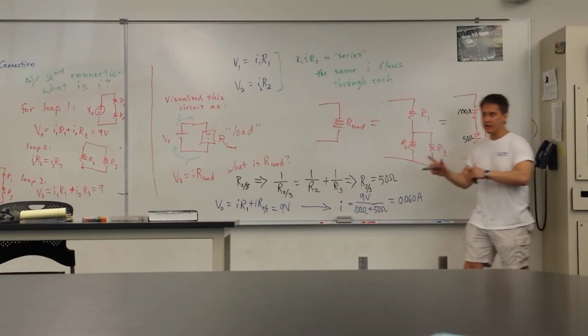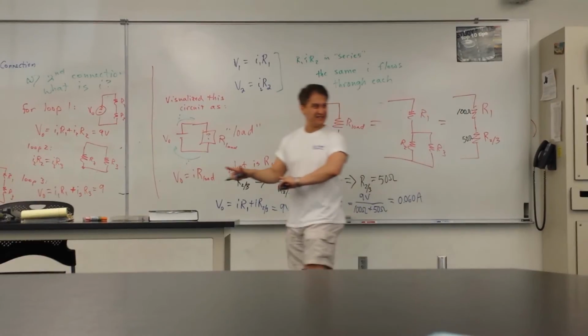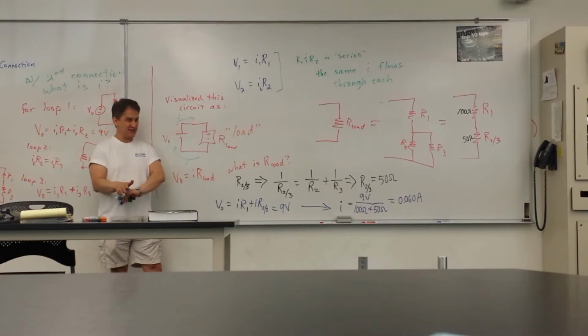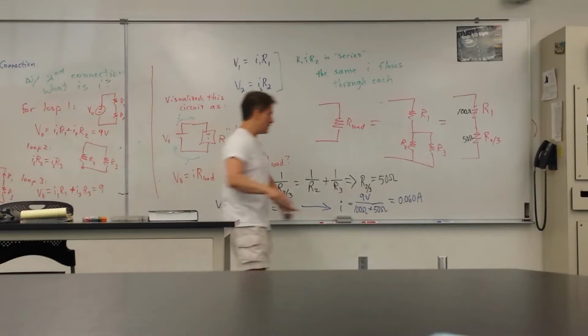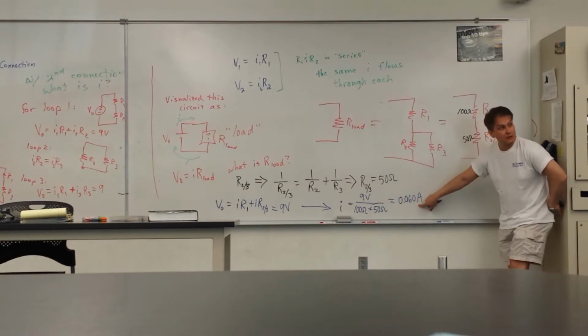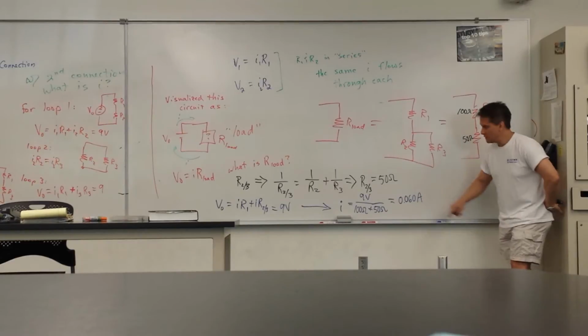So adding the connection, it's addition by subtraction, in a sense. Adding the extra drag, if you will, adding the extra resistor, actually lowers the total resistance. How much so? Previously, I was driving 45 milliamps. Now I'm drawing 60 milliamps of current out of my power supply.